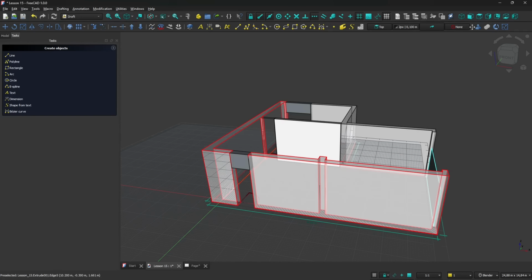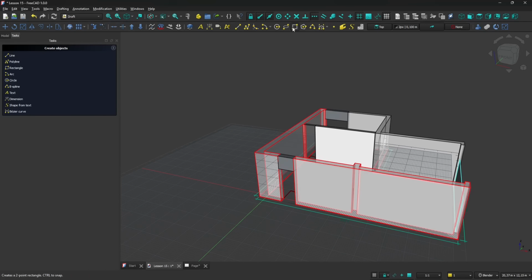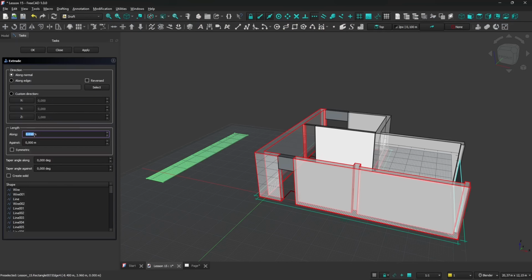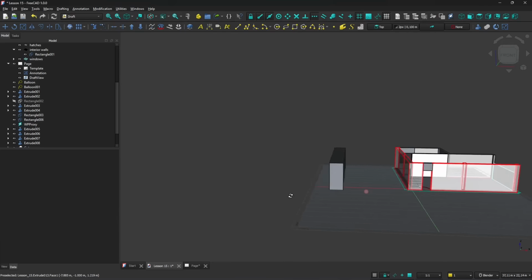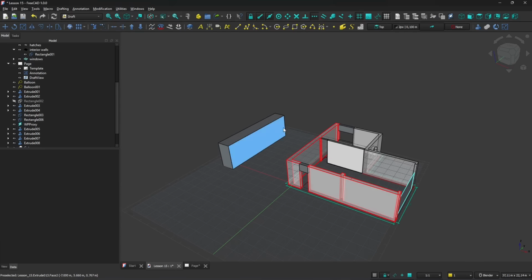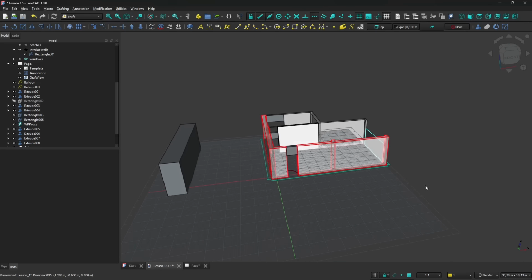So now I don't need to go to the part design or part workbench every time I need to extrude. So if I create something here right away, I can just click on extrude, type on the number here, the amount, and just click apply. And that's a way faster method to work on 2D and then build the 3D. And this is architecture, so it's pretty easy. We usually use extrusion, and rarely we use other modeling tools, but we're going to see the other modeling tools in the other videos. We're going to start also from this video.